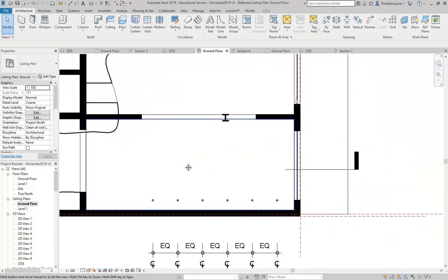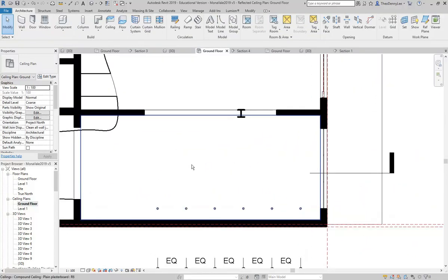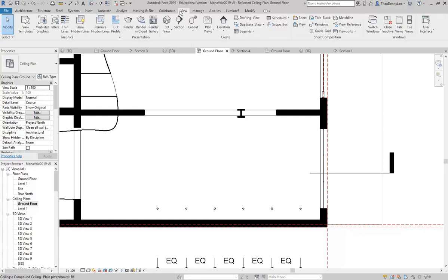So now, what I really recommend when you're starting to work with lighting for rendering is that you test it as you go. There's nothing worse than seeing people put in 1,000 lights and place them all beautifully, and then realise afterwards that none of them are actually giving any light in the render, or they're giving way too much light and difficult to control. So, I'm going to go and make a camera view, just up here on the quick access toolbar, or you can go to the view tab and click there again to get the camera.